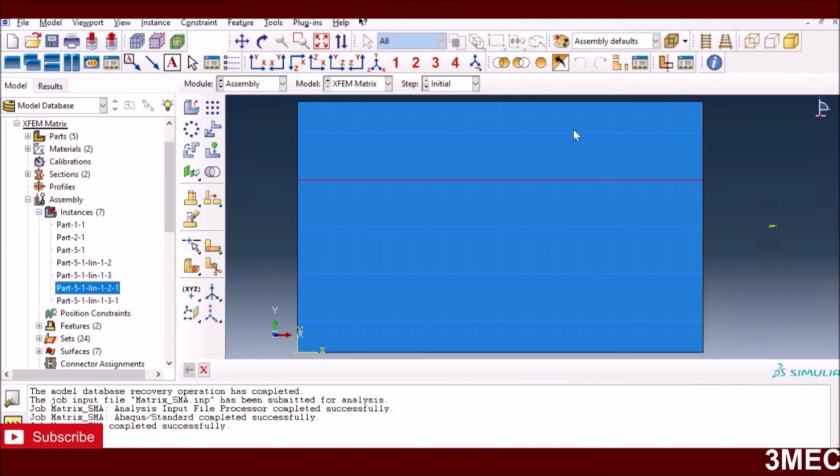So I have now assembled everything, but still they are separate. So ABAQUS doesn't know if these are all connected or not. In reality, these fibers should be somehow bonded. In the paper, they have given references and some assumptions they have made that these fibers are not bonded with the matrix, so they don't need to model any interaction between the two.